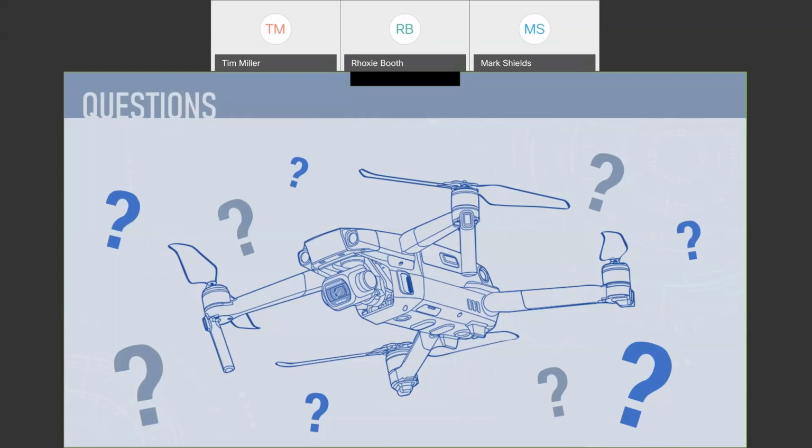Okay. And then can data be collected for 7 days straight on roadways? Also, is there a camera that can handle both day and night without having to be swapped out? Wow, that's a good one. For a survey like that, typically you would probably want to use something like a DJI Matrice, where you can set up multiple cameras on the actual unit itself. And if you've got it tethered, yeah, you could absolutely keep it in the air for 7 days. Okay. What is the max altitude with a tether? I think right now I haven't seen any tethers that are over 300 feet. I think that's the max altitude they've got right now.